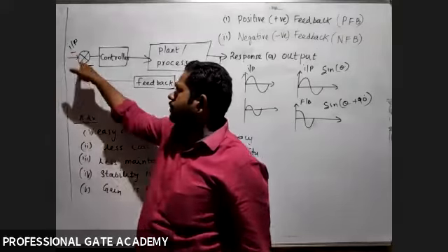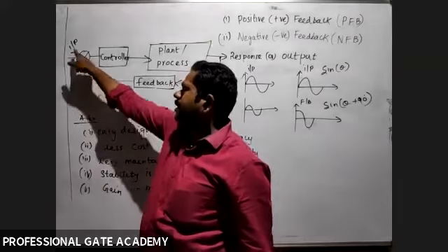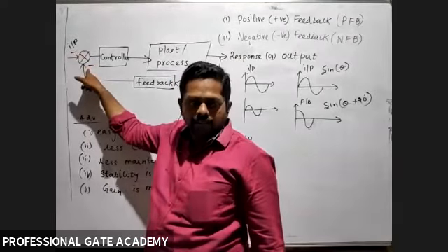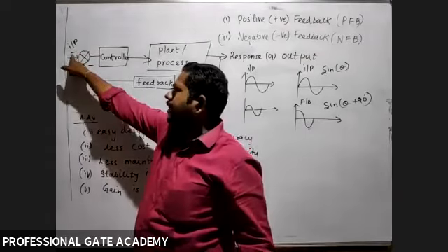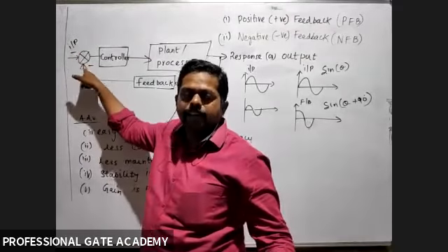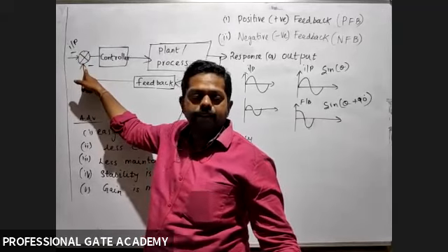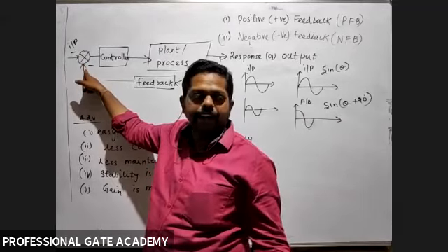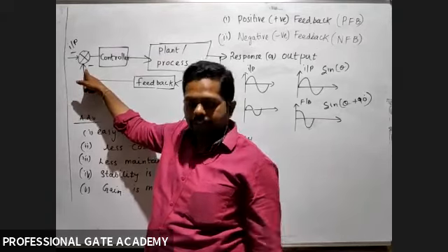Here, input has minus and feedback has minus. So both are in phase. This is minus sin theta, and this is minus sin theta. So are input and feedback in phase or out of phase? In phase. So is this positive or negative? Positive feedback system.